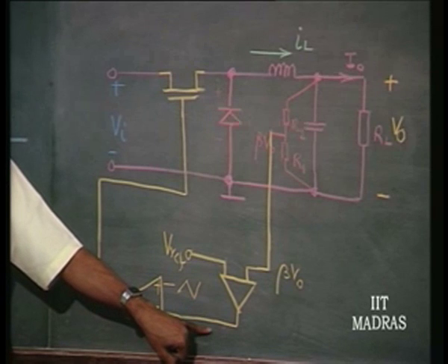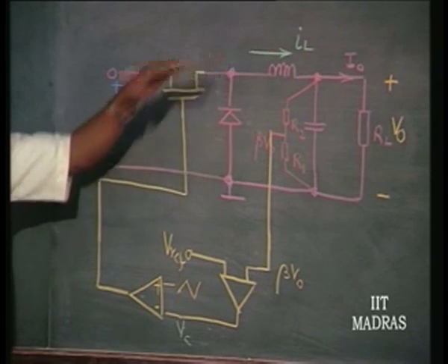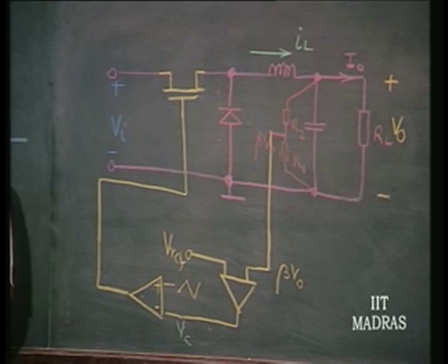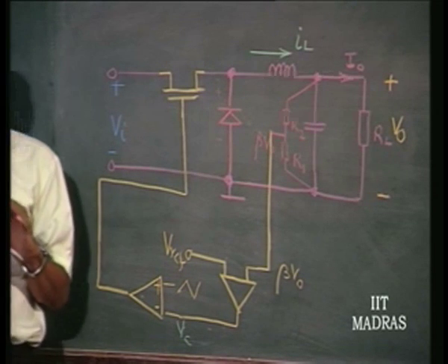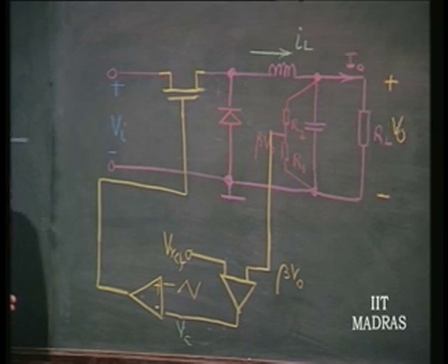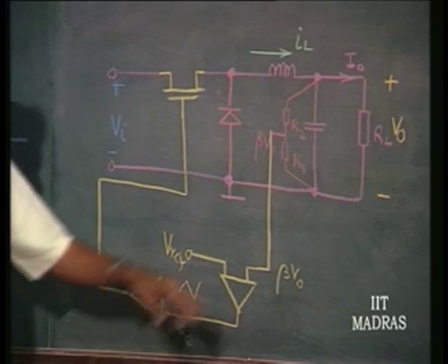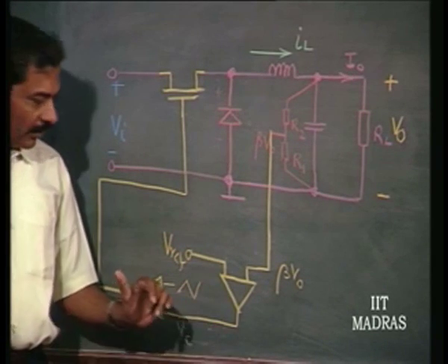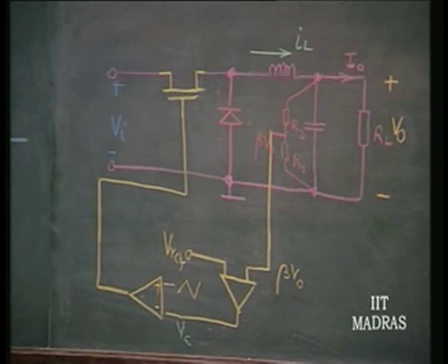such that this voltage here is going to be controlled, so that the switches are operating in either on or off mode, never in active region. Okay. This is made sure by this kind of operation. So, this is one of the most popular schemes for switched mode regulator.